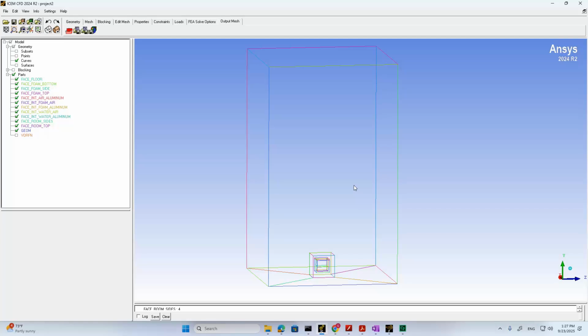At those boundaries, you will have to provide boundary conditions, which means those data at those boundaries should be specified instead of being solved. Otherwise solving those differential equations cannot give us a unique solution. You have to specify conditions at the boundaries of your mesh.